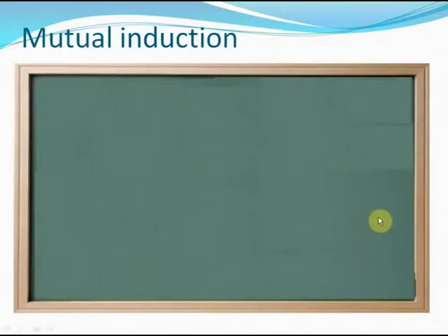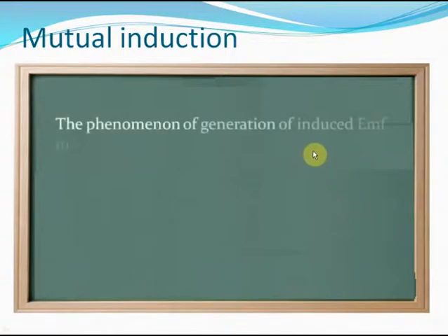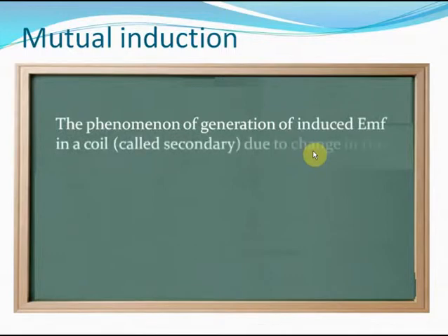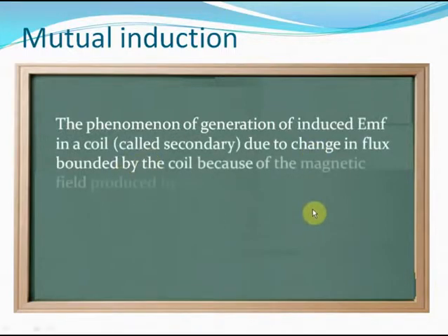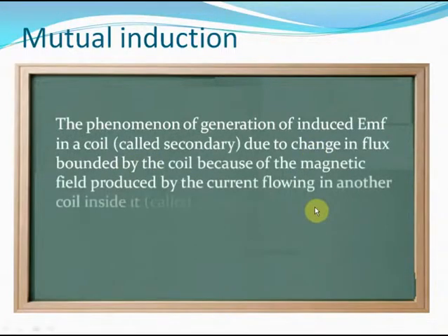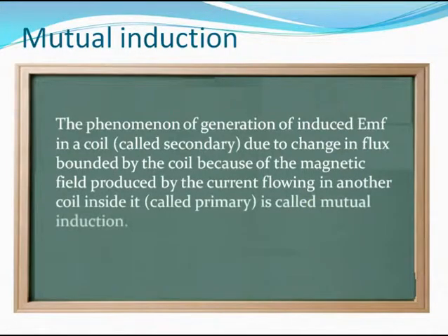Another interesting concept that's only slightly different from self-induction is mutual induction. The phenomenon of generation of induced EMF in a coil due to the change in flux bounded by the coil, because of the magnetic field produced by the current flowing in another coil inside it, is called mutual induction. Now this statement might sound quite tough, but it's actually quite easy.